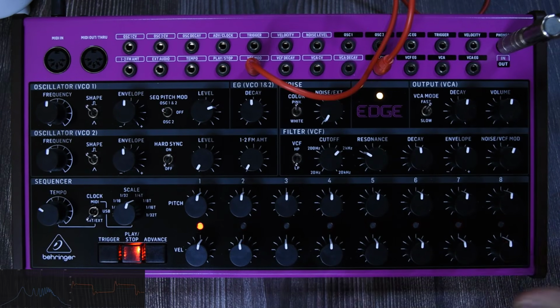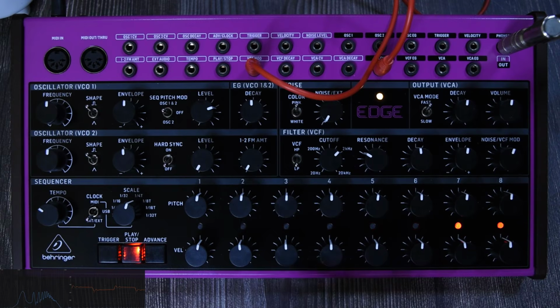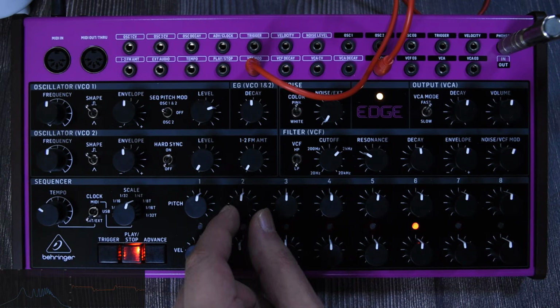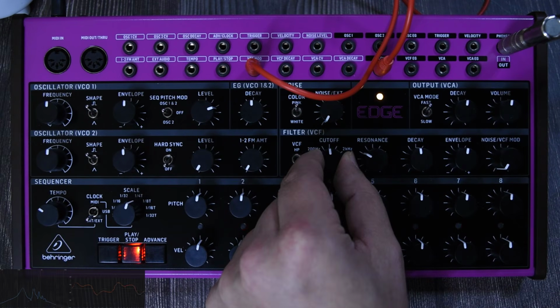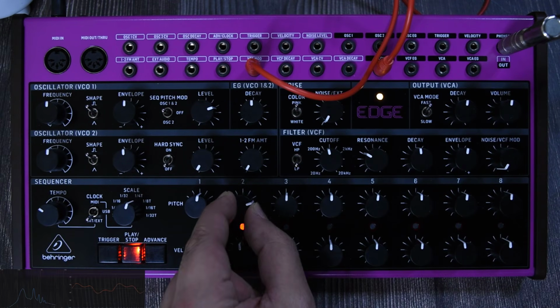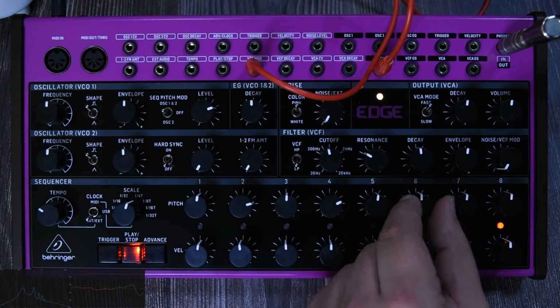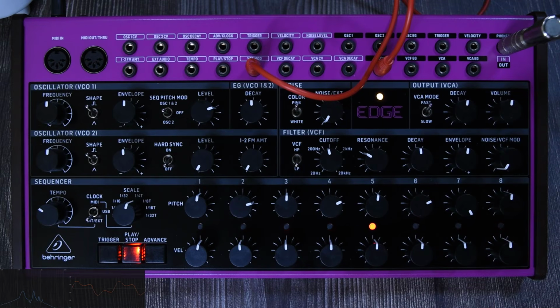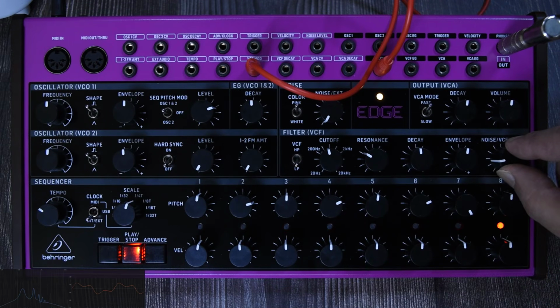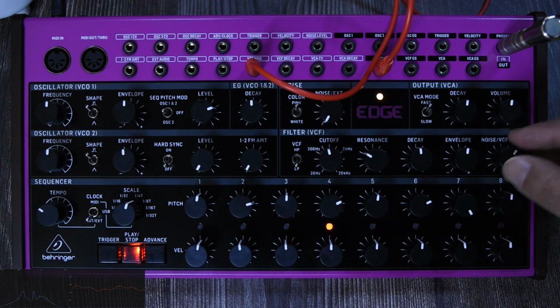I'm going to connect this and let's see if we get something. Remember, this is -5 to +5. Now, I'm going to go all the way down on the cutoff, and I'm going to be moving these knobs. Do we get something new? No, we don't. It is because this also works as an attenuator. If we go all the way down on this one, none of this is outputting anything. So with this one, we can control how much of this modulation we do. And in this case, it's going to be like an intensity type of knob.